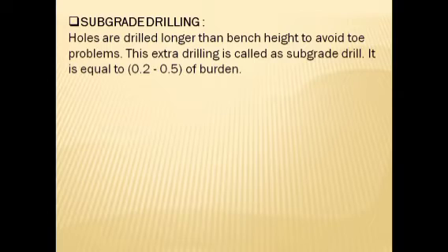Subgrade drilling. Holes are drilled longer than the bench height to avoid toe problems. The extra drill is called subgrade drill. It is equal to 0.2 to 0.5 of burden.